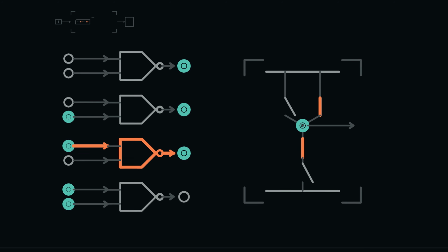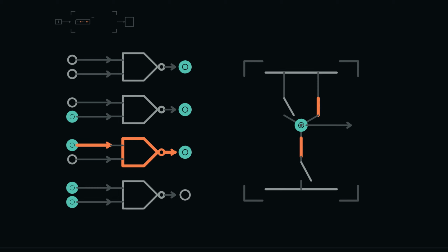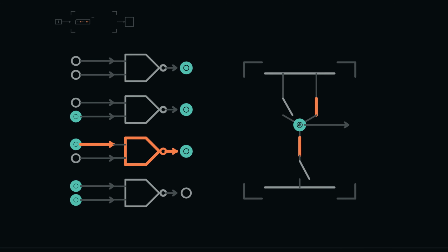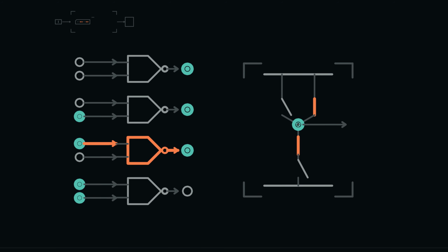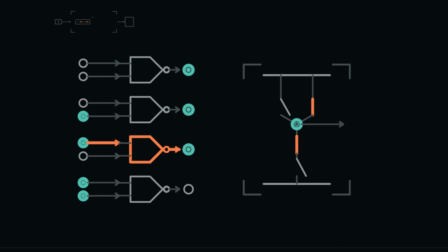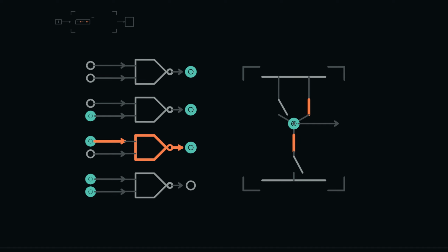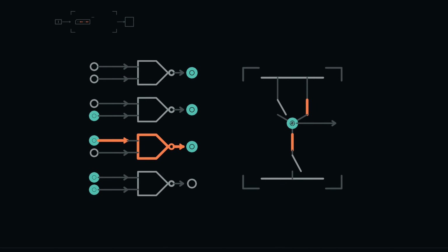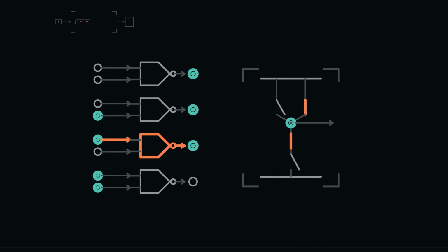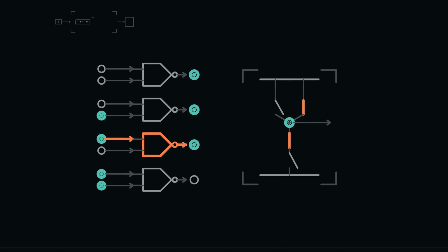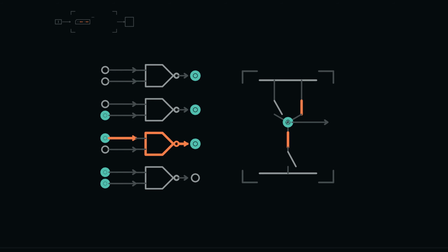A NAND output is the opposite of AND. Pass that output through the NOT construction and it becomes AND again. NOT each input first, and then NAND those results and the output becomes OR. It is 1 whenever at least one original input is 1. The next chapter will expose every wire and row of these constructions. For the present claim, we have a route from NAND alone to NOT and OR.